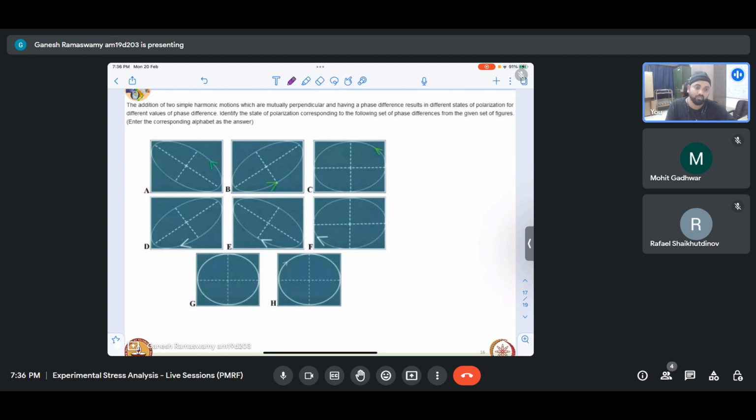Whereas now the photoelasticity method has matured quite a lot, and we have digital cameras, and using digital image processing, we can decipher the fringe order and the stress information at each and every point to a great degree of accuracy by using methods like phase shifting methods.